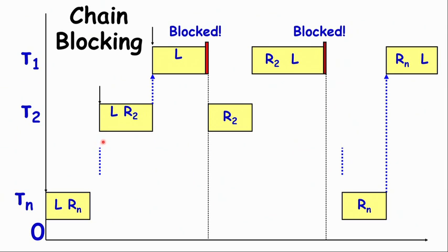Similarly, all other tasks lock their resources, and at that instant an instance of task T1 arises. It does some processing initially, but then it needs the resource Rn, and gets blocked. It needs the resource R2, and R2 is already locked by T2, and therefore T1 gets blocked. Now, T2 starts executing because T1 has blocked and the CPU becomes available, and it does local processing and releases R2, and then T1 gets R2, starts processing and needs R3, which is held by T3, and so on. So, for all the n resources, it undergoes priority inversion one after the other.